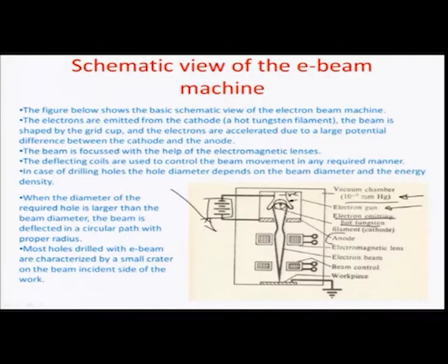And then there is a driving anode here which is also perforated in nature. So, this is a perforated anode, and the idea is that, as in most e-beam columns even those used for scanning electron or tunneling microscopy processes, the electrons generated out of this cathode are pumped through the voltage which exists between this anode and the cathode. Okay, so, the potential difference existing here is responsible for imparting kinetic energy onto the thermionically emitted electrons, and as they go into space they also get squeezed